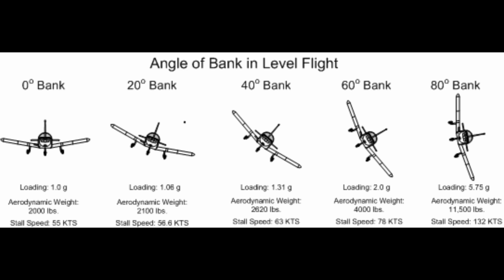An entirely different situation exists in aircraft design with maneuvering load factors. It is necessary to discuss this matter separately with respect to 1. Aircraft designed in accordance with the category system, i.e., normal, utility, acrobatic, and 2. Older designs built according to requirements that did not provide for operational categories. Aircraft designed under the category system are readily identified by a placard in the flight deck, which states the operational category, or categories, in which the aircraft is certificated.